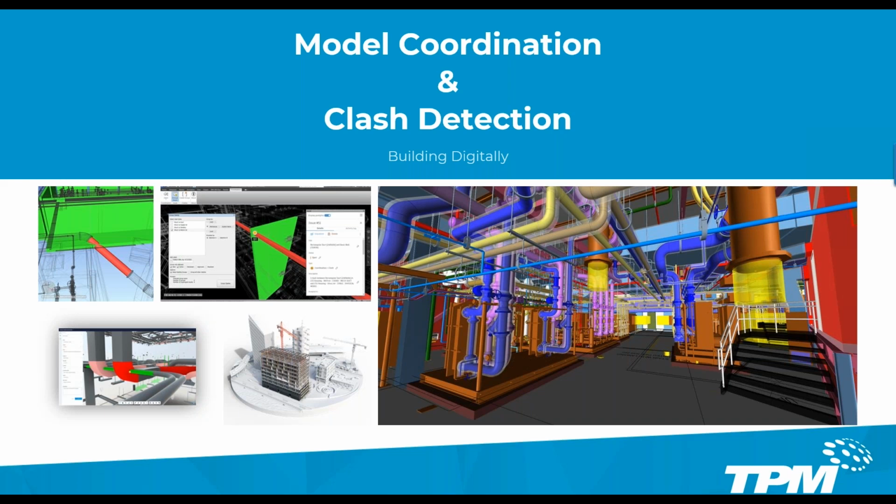And then as your project progresses further into that design and drawing development, these models would end up becoming more and more realistic, like the image on the right there, with hangers and a lot of that sub trade partner information. So that allows the project team to really build that building digitally first. And that clash detection process is a pretty tedious process, but it allows you to identify and produce RFIs that you might not see for months until you're standing underneath in the field.